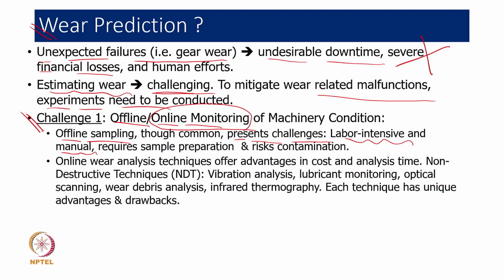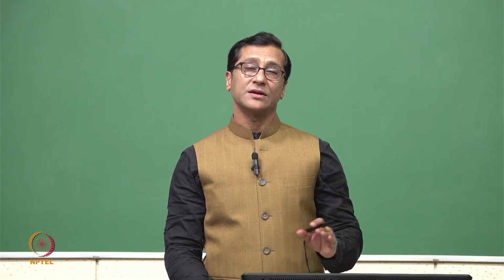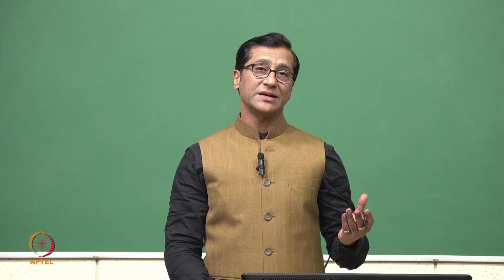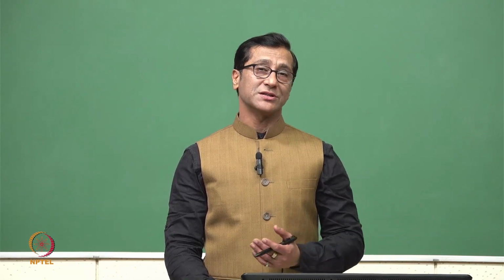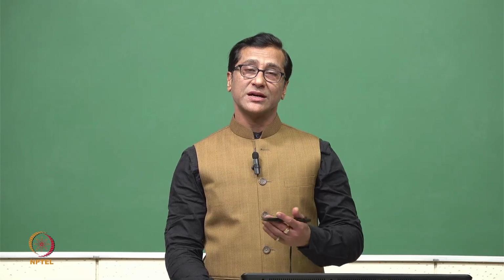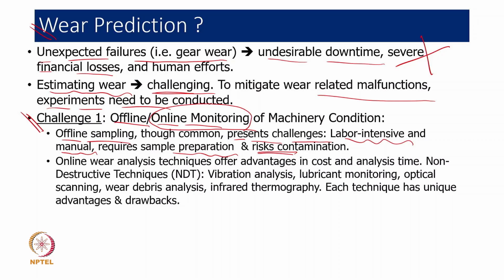Sometimes we do have some sort of contamination, or it also requires sample preparation. Many times a sample which is prepared, and if you are investigating after 4 hours, 6 hours, 10 hours, that sample gets contaminated. Even though you cut the gear teeth and then go for estimation, it will get oxidized, and some other contamination comes in, which was not a cause of the failure, but when we diagnose, that kind of contamination also gets estimated. So we need to really get rid of those things.